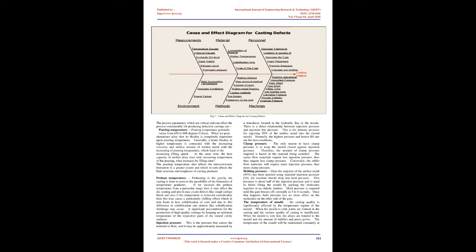Die casting of metals is the highest technological level of casting metals and their alloys into metal molds. The quality of pressure die castings is affected by numerous technological factors, such as pressing velocity during a casting cycle, increase pressure, and time of filling a mold cavity. 7. A stable finite difference scheme, the component-wise splitting method, a 3D thermal analysis system has been introduced and adopted in the mathematical modeling of the heat transfer problem in the die casting process.